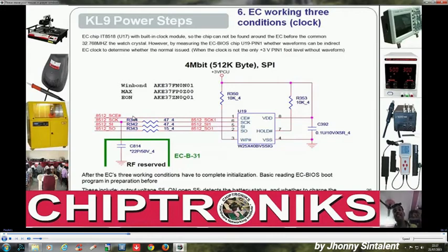The ADS strobe is the first signal generated by the processor. So if we are able to locate the ADS strobe, then we can say that the processor has worked okay. So we can check all the signals through the oscilloscope, and in my oscilloscope class we'll discuss all of these things.